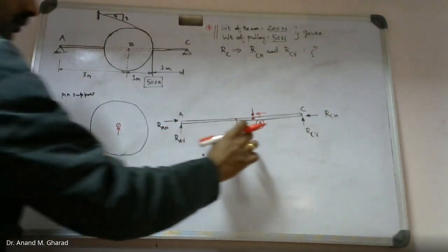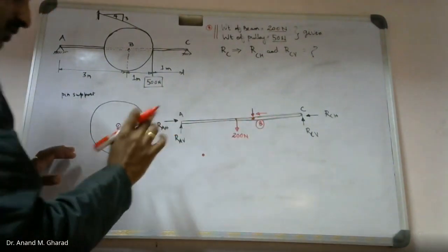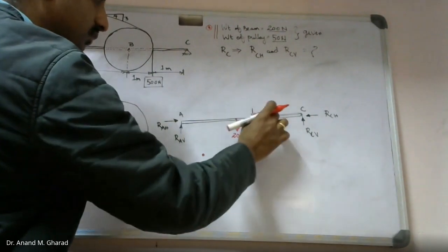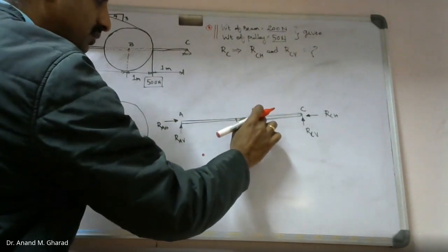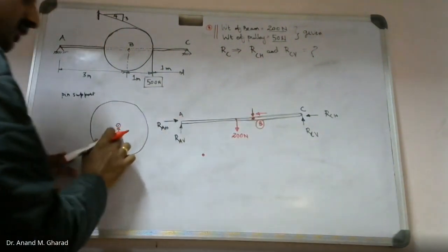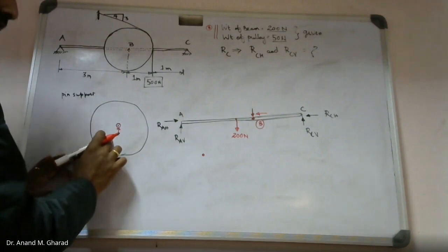But while representing the free body diagram, you are supposed to be very careful, because if I assume the direction of the reaction force to be in this way for the beam, then equal and opposite direction should be represented on the other rigid body, right?